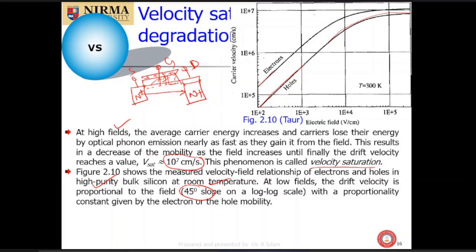Moreover, at the interface we have discussed that there are imperfections in the bond, defects, because one material is SiO2 and another one is Si. A perfect covalent bond will be in the further area, but not at the interface. So those interface states also act as traps.